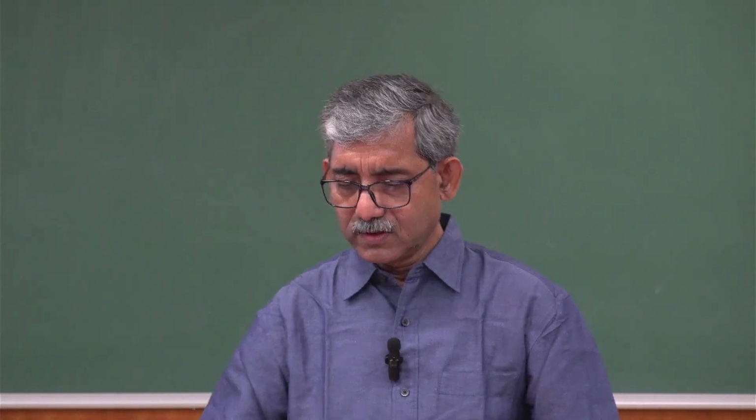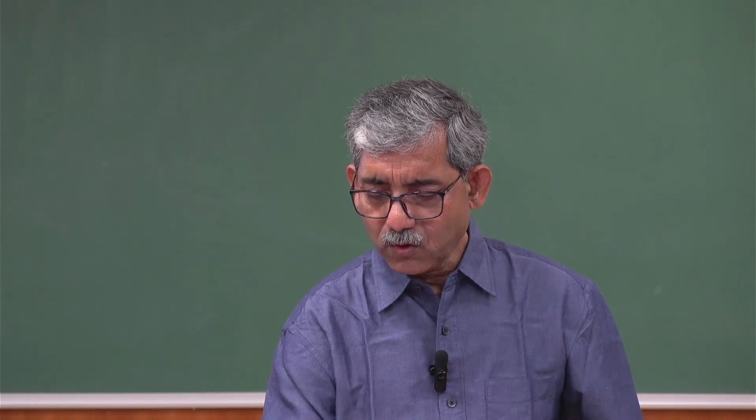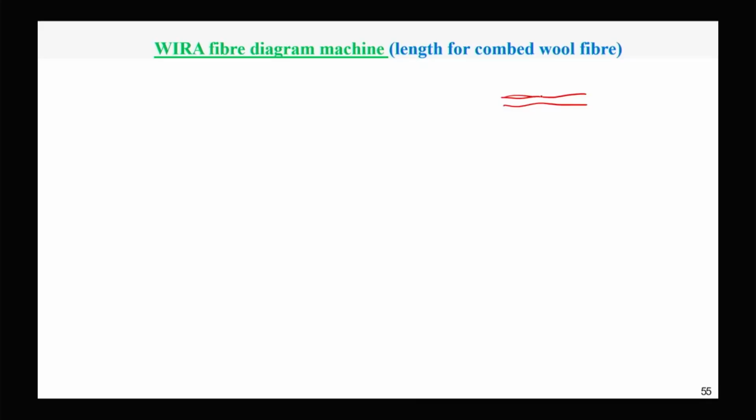And suppose in case of cotton, we are making a fringe, and the principle of measurement in the automatic machine, typically for cotton, is a photoelectric method, where light passes through and we can measure the number of fibers or density of fibers, that we have already discussed.